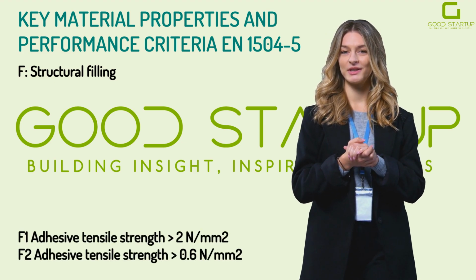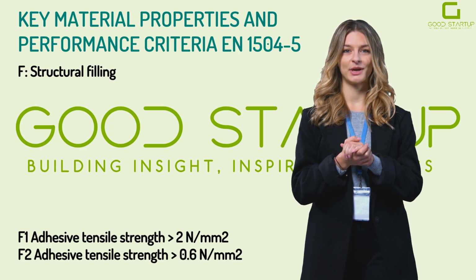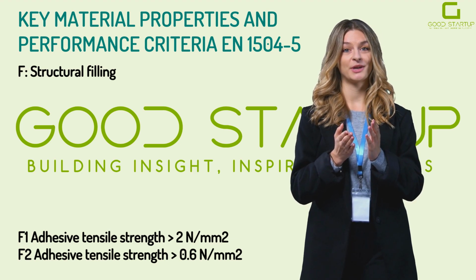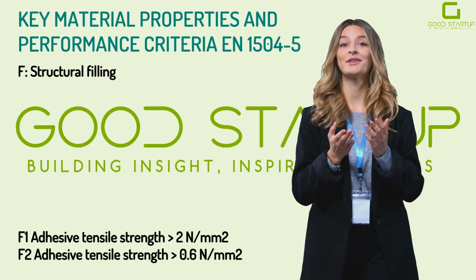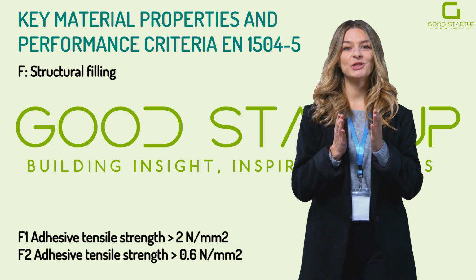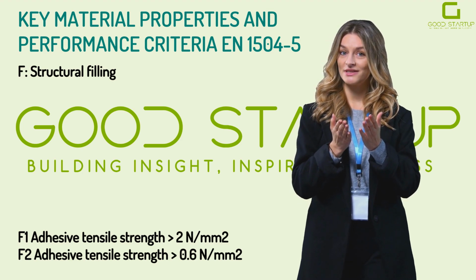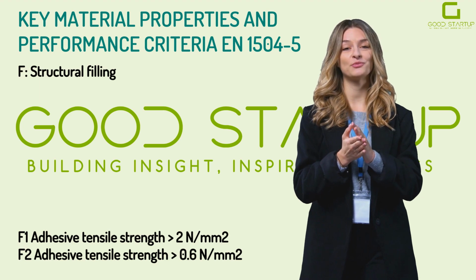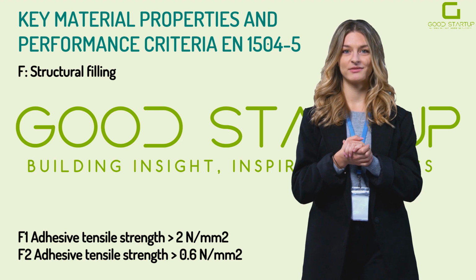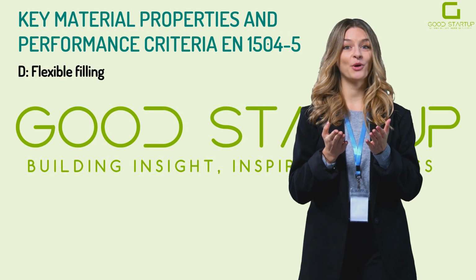The bond to concrete, measured as adhesive tensile strength, must meet minimum values. Category F materials need high strength. For example, F1 class requires at least 2 megapascal bond strength to concrete. This ensures the injected material can transmit forces across the crack without debonding. In practice, structural epoxies often far exceed this value, providing excellent adhesion that can even exceed the tensile strength of concrete itself.